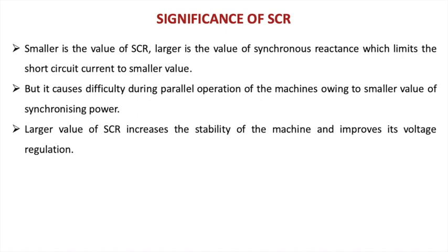The larger the value of SCR, the more the stability of the machine increases and the better its voltage regulation. When we defined the phasors, we saw the angle delta, which is the angle between the stator field and the rotor field.